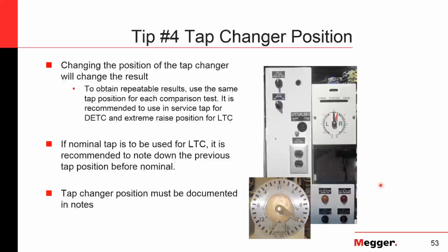And then the LTC, of course, this is varying during the load while the transformer is in service, so you never know at what point that's going to be. So what you recommend there is to perform this test when the LTC is in the highest raised position. This way, every single tap's in there.